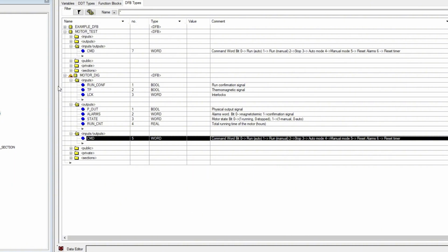This technique is fundamental for two compelling reasons. First, for safety, since it prevents an order from getting stuck or active indefinitely if, for example, we lost communication with the SCADA right at the moment of the maneuver. And second, for programming cleanliness, since it guarantees that our interface buttons always work as physical push buttons. The operator presses, the PLC executes, and the system resets itself, remaining ready for the next order without the need to program edge logic or additional resets outside the block.